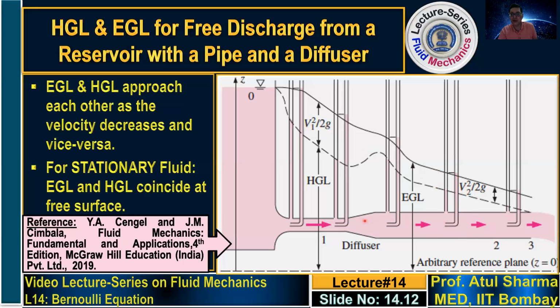Whereas when it is passing through this diffuser, the static pressure is increasing. So this hydraulic grid line consists of a combination of the static pressure and the elevation. The elevation that we consider in this problem corresponds to the center line passing through this pipe, and that elevation is the same along the axial direction. What is varying is that when it is passing through the diffuser, the static pressure will increase and the velocity will reduce. So the gap between these two lines will reduce.